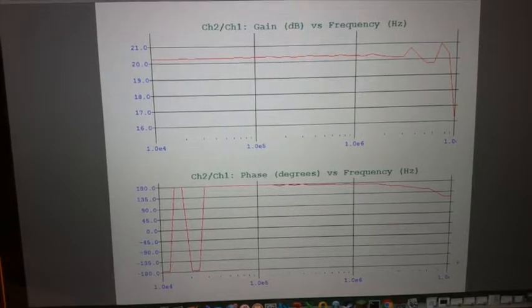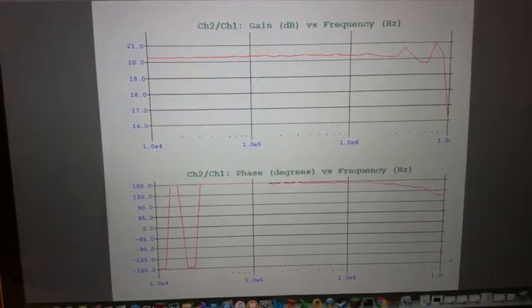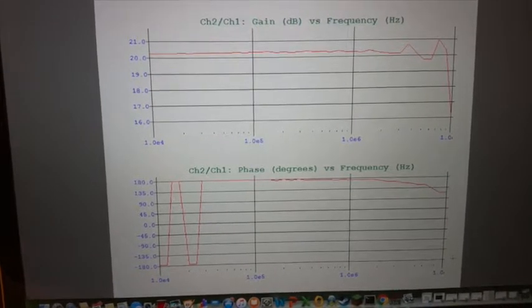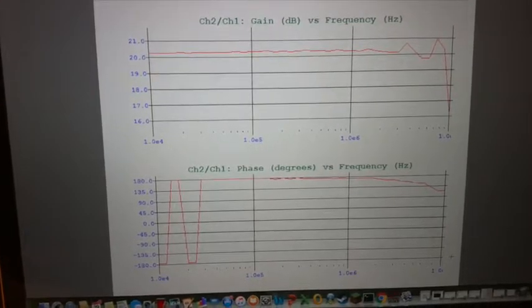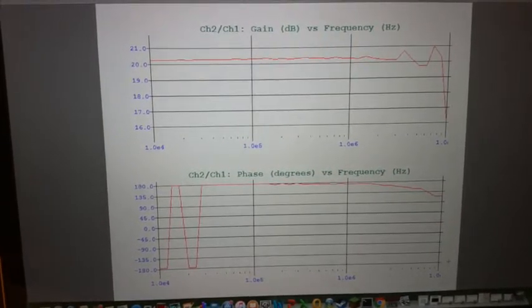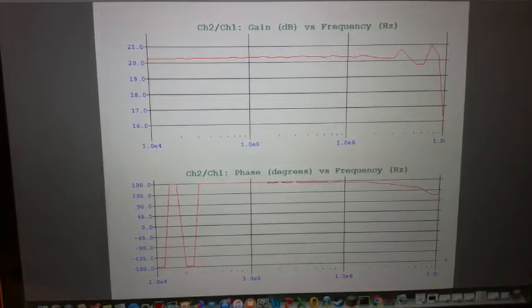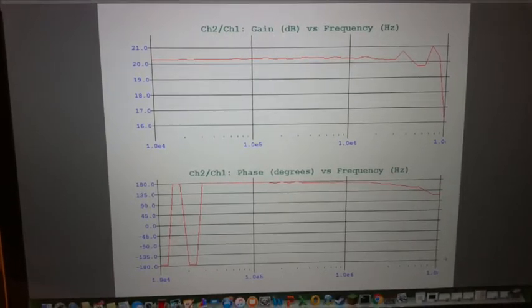You should also note that the phase shift is 180 degrees, so VO2 is 180 degrees out of phase with VN, which is to be expected since we saw in part B that VC was positive for negative input signal and negative for positive input signal.